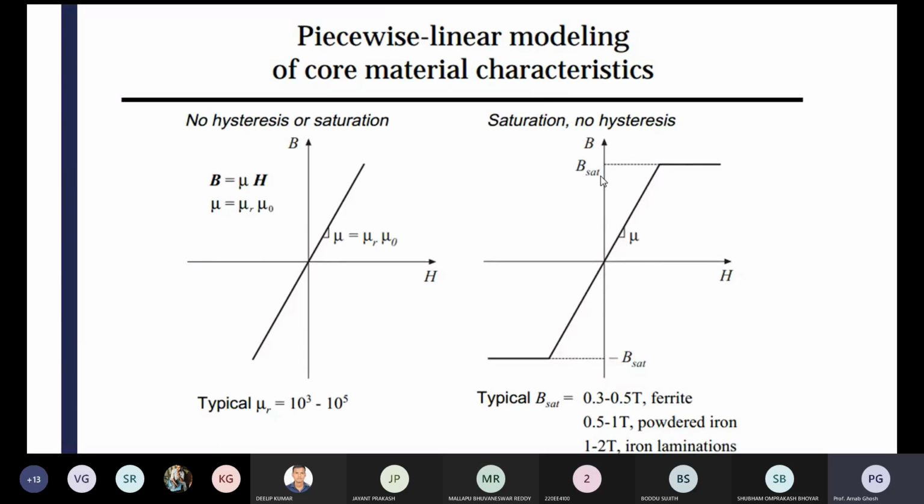After getting that amount of current, you have to select the core. For the selection of the core, you have to understand which core you are going to pick. If the current is high and you use the wrong type of core, the B saturation will be very low. That's why you have to select a ferrite core having more B saturation.